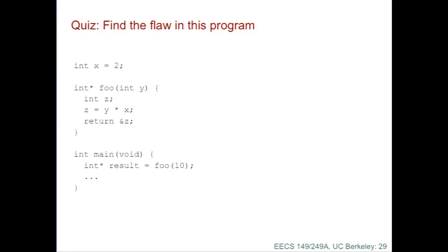You're going to get a result, and you're going to use the result a few lines later, and it's going to be the result. And you're going to think your program is correct. But it's not. And the program is actually extremely vulnerable. In particular, one of the things that could happen is between the time you assign this result to this variable and the time that you use it, an interrupt might occur due to a timer or an I/O device, and a whole bunch of stuff will get pushed on the stack because a bunch of procedures will get called, and the result will get overwritten with some random value, and then when you go and read the result, it'll be something quite else from what you expected.